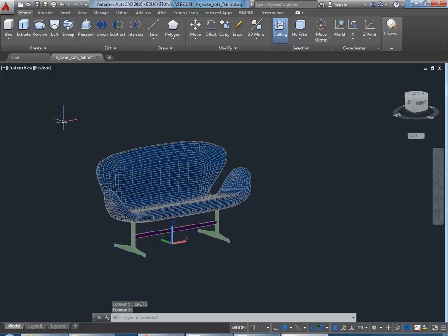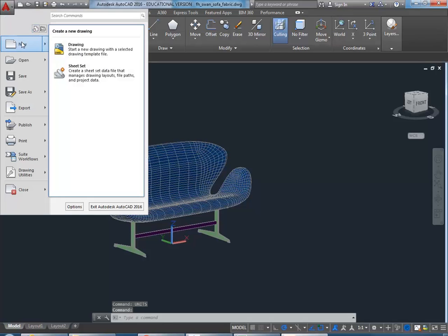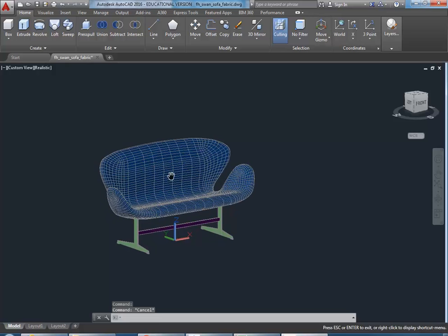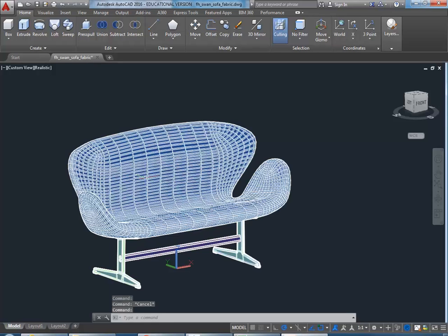Actually, that's probably what I'll do. You could go and make a new file in AutoCAD, and then using that units dialog box, make sure that's set to inches in the new file. Not this file; it doesn't matter. And then when you insert this file into that one, it'll scale it from inches to millimetres. So that's the way, if you've got to use it in AutoCAD at the right size. But like you were saying, we'll do it in Revit, and that saves a step.